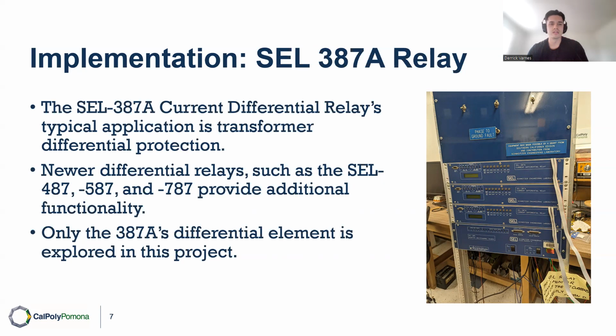In the 387A, there are 4 different elements available for protection. You have a differential element, an overcurrent element, a temperature monitoring element, and I can't think of the fourth off the top of my head, but in this project we only focus on the differential element.